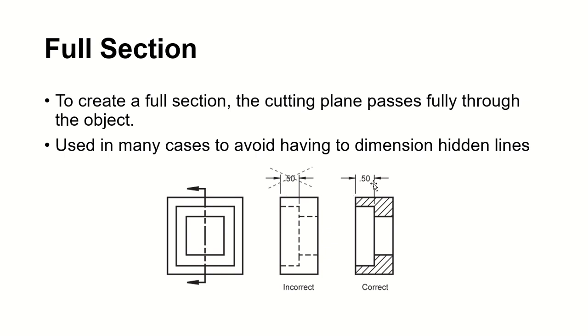We are going to put it this way because here, look at that, we have no section lines. That's an internal feature, so you definitely need to put the section lines like this, so this is correct. We put section lines parallel to each other, 45 degrees to the angle. This is the same part, so the lines are oriented in the same way.